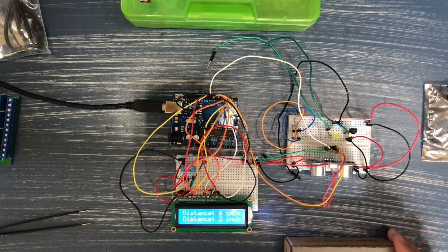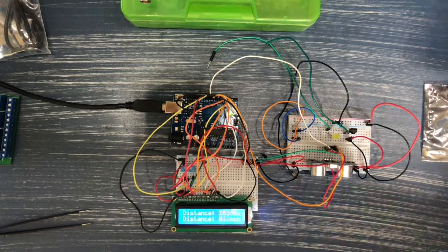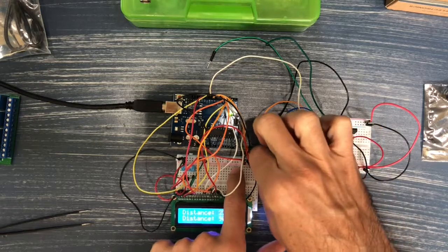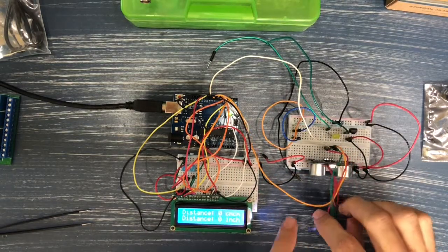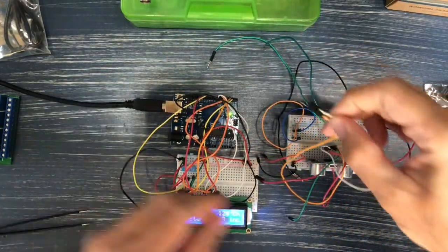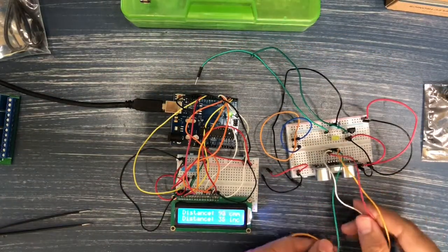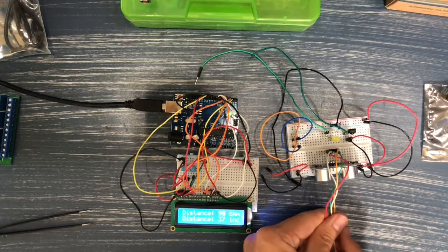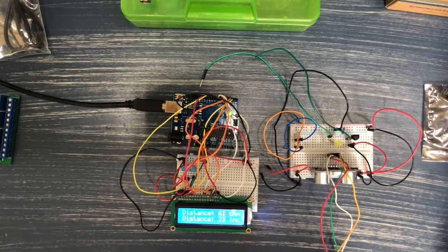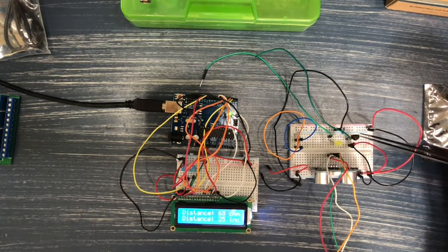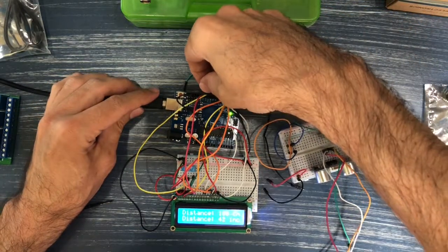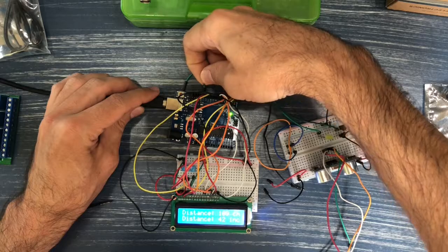Okay, so we have looked at 2 examples of loading code up to an LCD screen. And the cool thing about this is that you only need 3 lines at the beginning, like we reviewed, and then the LCD.begin in the setup, and the LCD.setCursor to place your cursor wherever you want to write, and finally the LCD.print, which is basically what you use to print out data onto the screen, much in the same way we did with the serial monitor. And it's that simple. Alright, so let's go ahead and look at the next sensor.